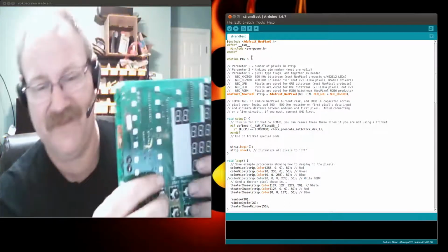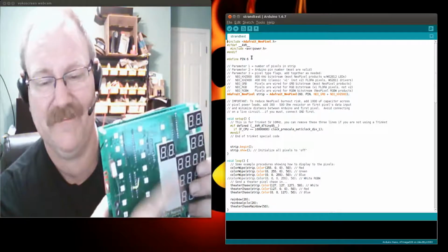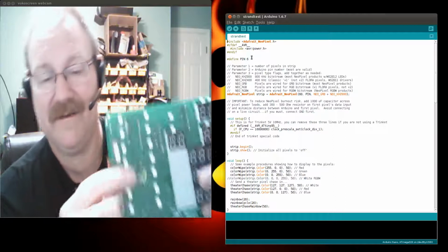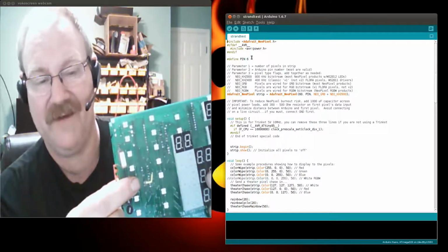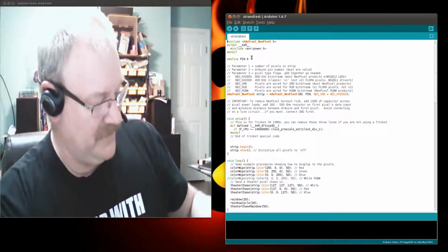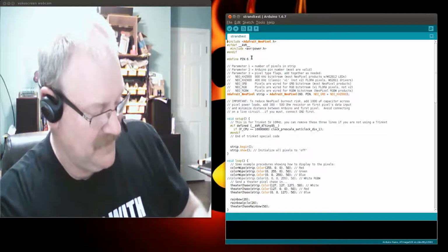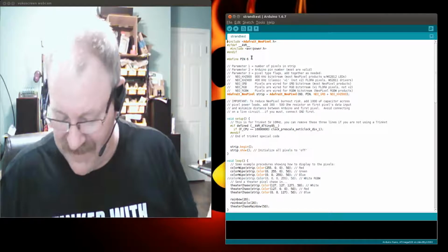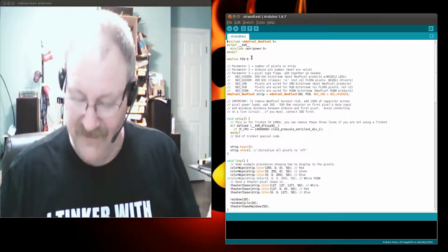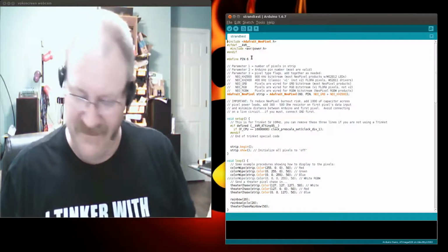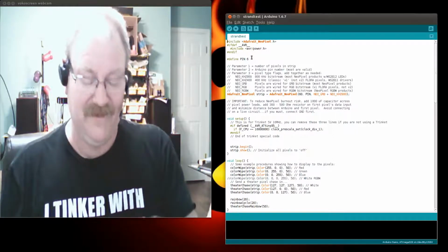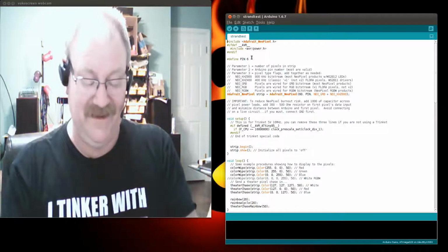Actually, the very first green boards had to have a couple wires flown on them because they had a couple miswires, but they work. Still the same. It's just one little jumper that hooks something up that was missed when we designed it. We do our best. There's like 1,000 traces on it. Just missed one. So we're going to take our board and we're going to take a 470 ohm resistor.